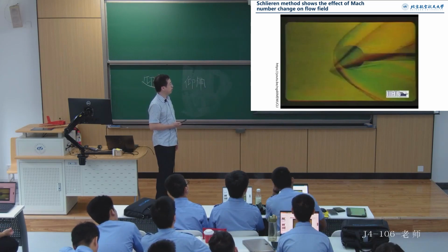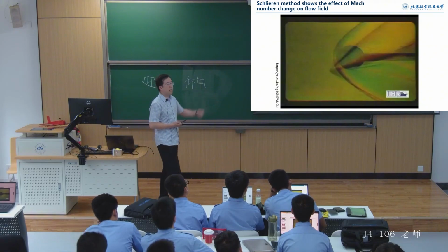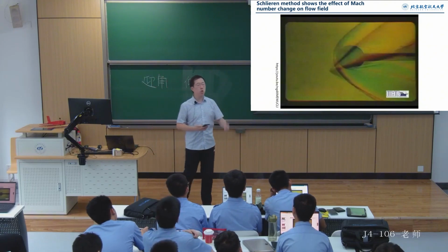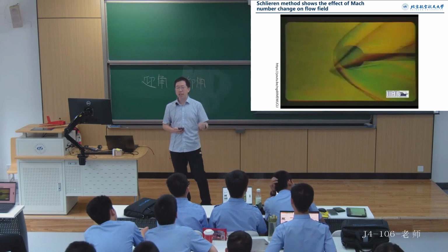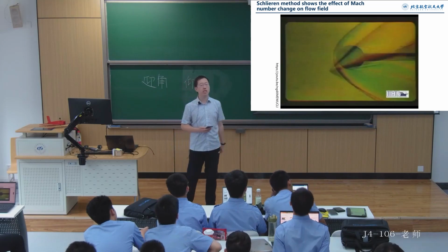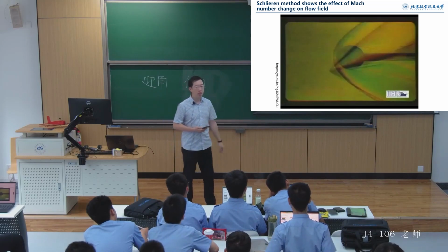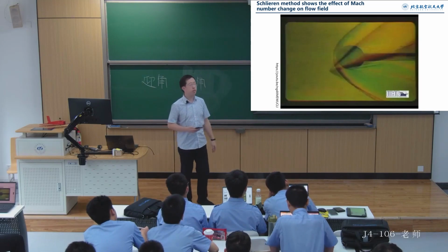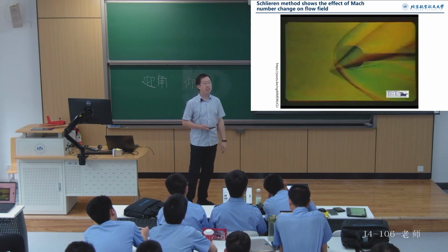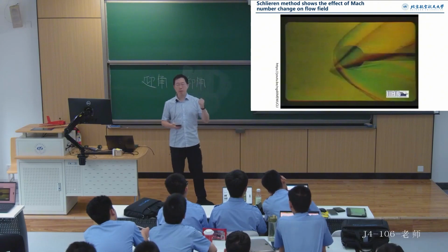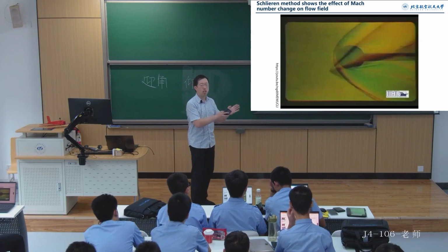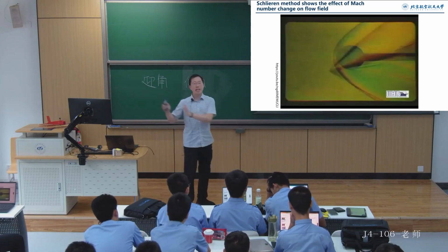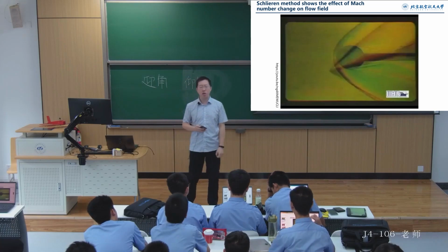Here, the impact of the Mach number on the aerodynamics of the aircraft is mainly evident when the aircraft speed is relatively high. At this time, due to the manifestation of air compressibility, it affects the aerodynamic forces. We might introduce this to you later in the semester. In short, as we mentioned earlier, if we want the aerodynamic forces measured on a small model in a wind tunnel experiment to be comparable to those on a full-scale aircraft, we need to meet the corresponding similarity conditions.